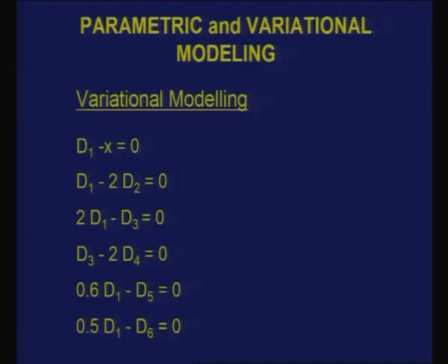And this aspect is now manifest in many of the CAD packages. What you basically do is variational modeling, like when you practiced building the parts, you went through variational modeling. Constraints can be directly imposed in terms of the values also, and the constraints which we looked at need not be purely in terms of dimensions, you can also have geometric constraints.